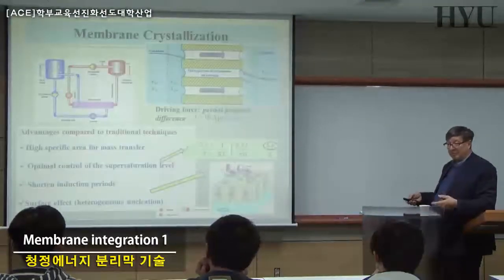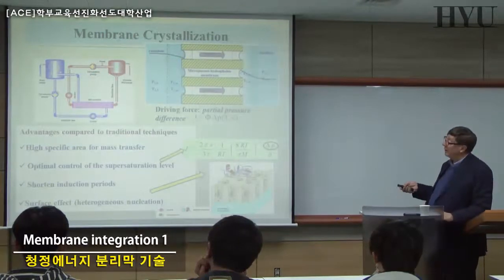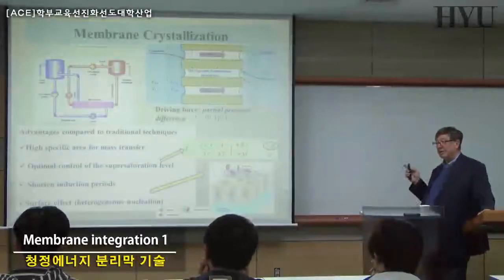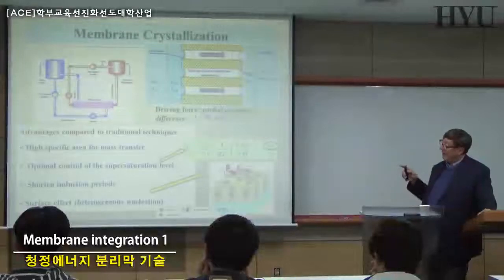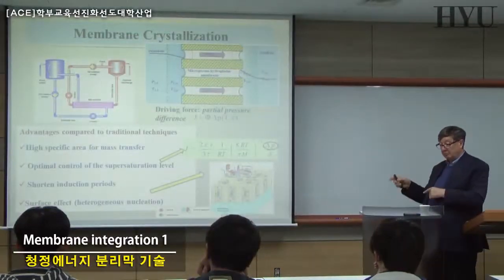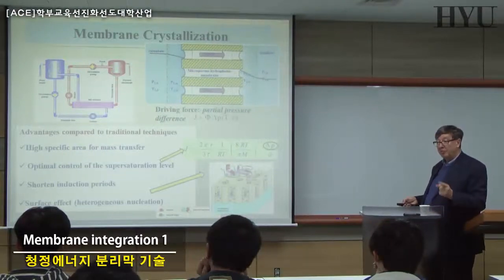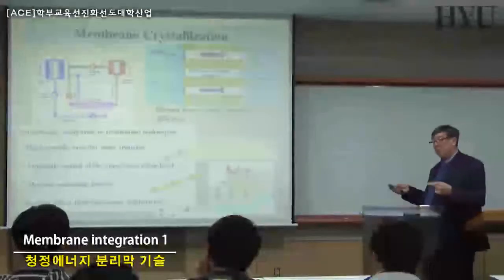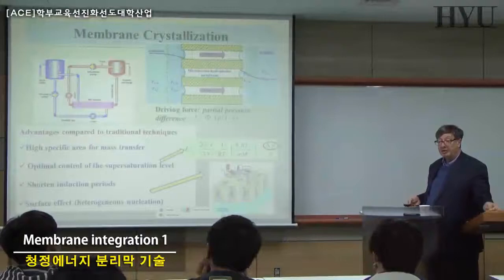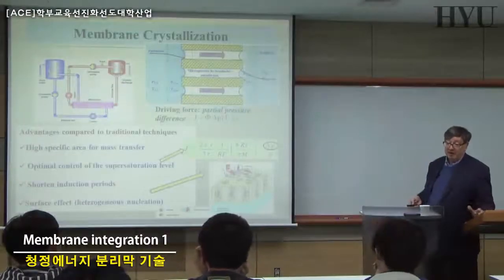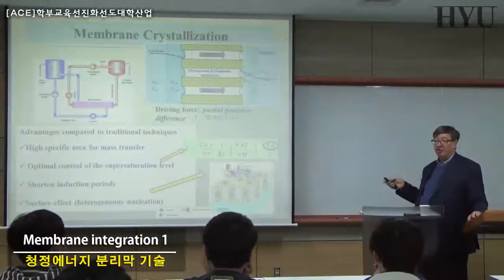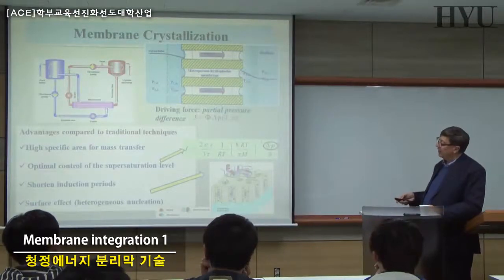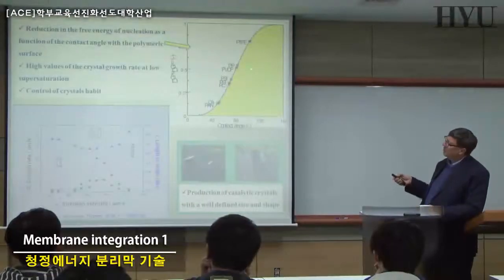Membrane crystallization is something that will also follow, and it will have exactly the same kind of properties. We can crystallize, not just concentrate, but crystallize our solute in appropriate final habits, to the point that we can produce the polymorph which is necessary. That means, for example, you don't just produce magnesium sulfate, you produce it in the form of epsomite. You don't just produce sodium sulfate, you produce it in the form of thenardite, etc. For each one of these systems, if good researchers do their job, it will be possible to produce at a very high